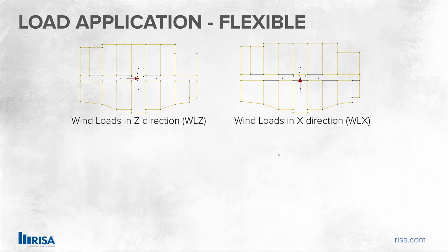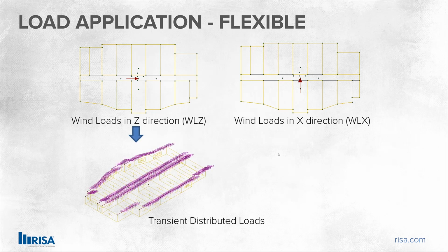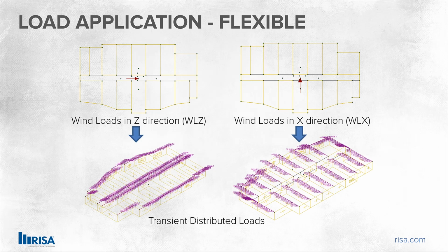Now, the next application obviously is a flexible diaphragm. For flexible diaphragms, loads are applied in the center of the model in both directions prior to the solution. But then during the solution, something else happens. During the solution, the point loads are broken down and applied to elements based on the tributary area. And so we see these as transient distributed loads. We'll go ahead and take a look at that in our RISA-3D model.